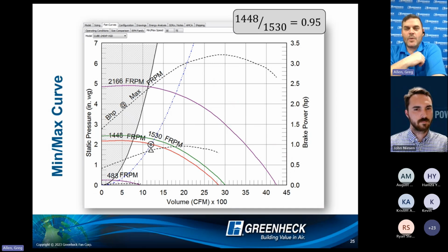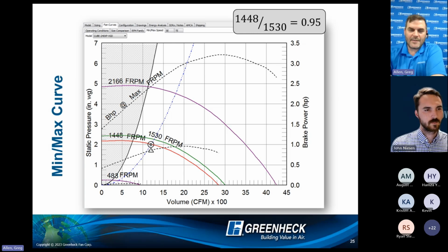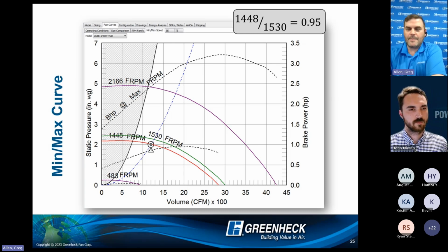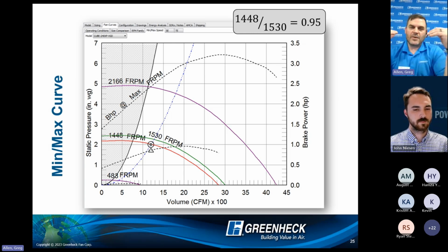So in this scenario, if I put an EC motor on this, and the 1 horsepower motor is going to run out of horsepower at that 1530 point, I'll actually program in the ceiling for that motor's function. I'm going to program in 1530 fan RPM max. And when you define a max point, that defines what 10 represents and scales from there.